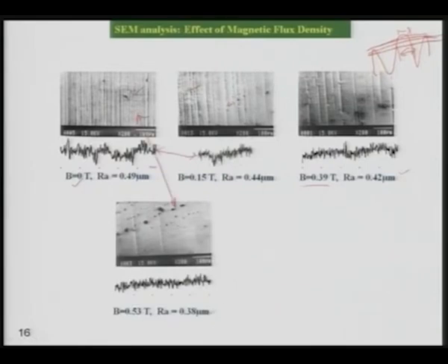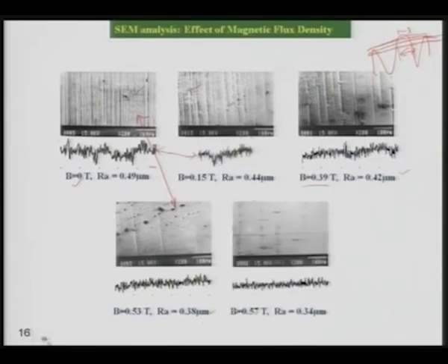They have sheared large number of peaks, and it is becoming more or less the flat surface, and then you get 0.34, and you can see the difference in the last two figures. That means this is a better surface than this left hand side surface, and its RA value is 0.34 micrometer. So it clearly indicates the effect of magnetic field on the rate of finishing in case of MRF process.